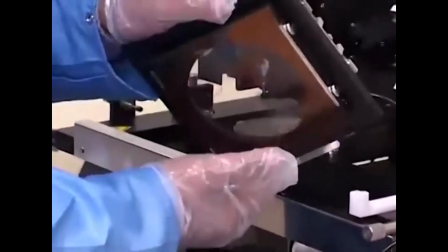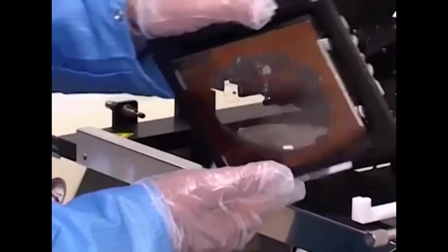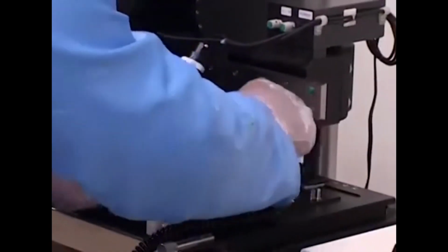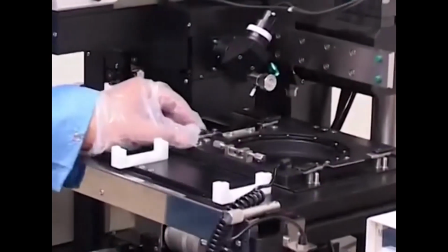So what we do is we take this wafer holder out, and it is pretty much firmly gripping the mask now, and there is no possibility of the mask falling, as you can see. So we go back into its position here and then try to mount it in a manner so that you can actually bolt this mask holder onto the top of the wafer surface. So there are 4 bolts for that purpose.